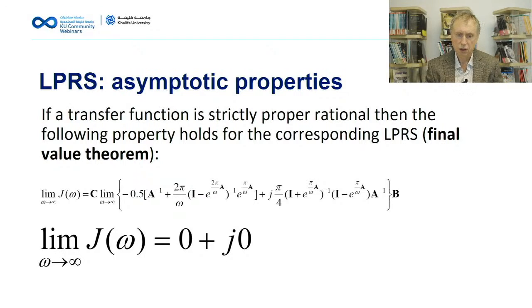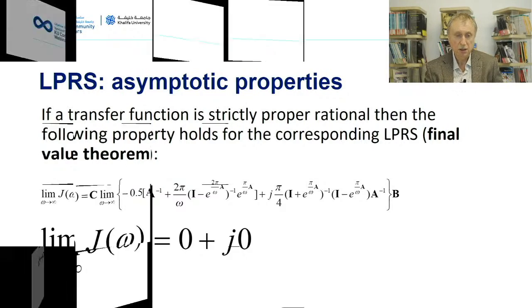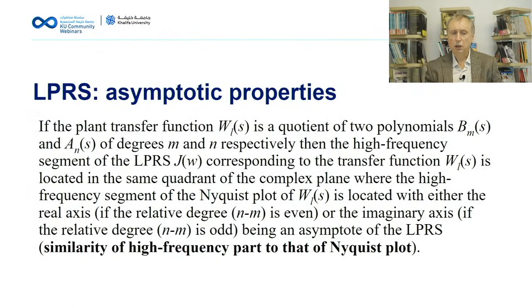If it has delay, we will have a different situation in this case. Also, what is remarkable is that the high frequency asymptote of the LPRS is similar to the high frequency asymptote of the Nyquist plot, which is a very useful property for us.